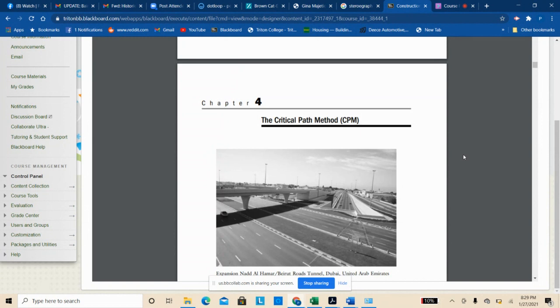You might break up shop drawings for cabinets and fabrication of cabinets. Even though you're not doing anything, it's kind of a dummy task. It's still there, and it has to be recognized. It is preceded by the down payment on the cabinets. So yes, you would definitely have some kind of indication early in the chronological order, because everything is going to kind of base off that too.